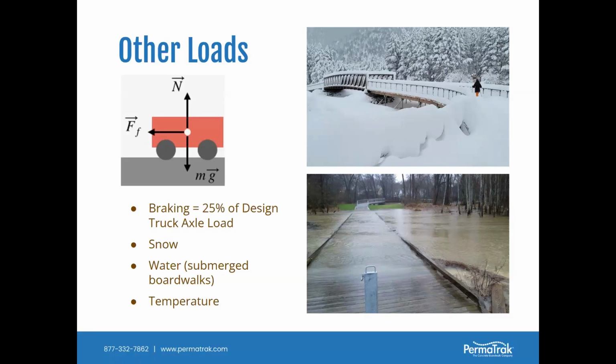Snow loads, certainly in the higher elevations, is critical. This top right picture is in South Lake Tahoe, and we were required to design for 240 pounds per square foot loading, which is significant snow load. And that's serious loading, especially for that bridge in the middle, as you see spanning from one boardwalk to the next. That certainly could control the design, and it probably did for the truss bridge. It definitely did control for the boardwalk that you see on the near side of the bridge.